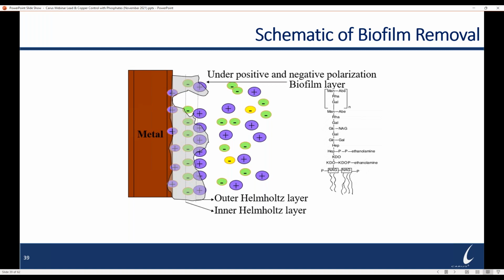In the case of a well cleaning, because they're trying to clean that well up immediately and very quickly, they might dose 1,000 parts of a polyphosphate product to break up that biofilm. And then they'll come back with a dosage of 1,000 parts of free chlorine to disinfect that pipe, and then flush all that to waste and test the well to see what the bacteria count is after they've done this cleaning. They'll also look for flow rate improvements as well. Sometimes they might do a mechanical cleaning and then this chemical cleaning to help break up this biofilm and remove it in a well application.